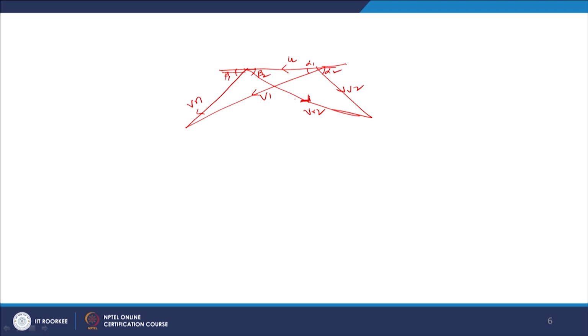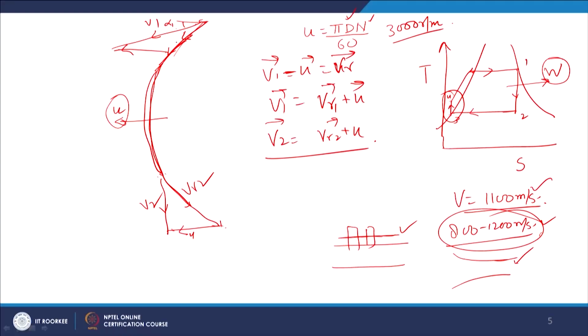Now, nozzle outlet angle is important in the case when we have to do multi-stage designing of the turbine, right. At what angle the steam is coming out of the previous stage, and then it has to be reoriented, and then it will go to the next stage. Okay. So, now there is a loss, because ideally there should not be any loss, but there is a loss in the course of travel over the blade surface. So, relative velocity reduces in practice.